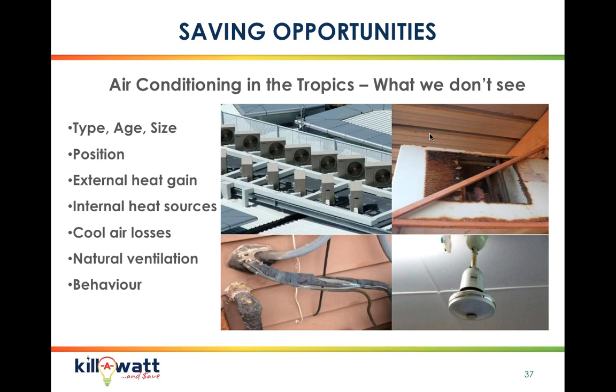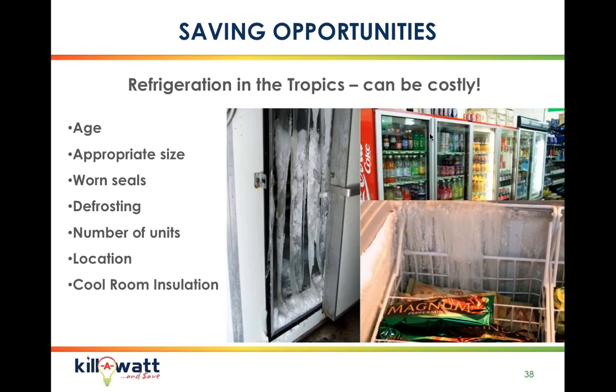In the far north, we see a lot of insulation breakdown. This is often not picked up in maintenance checks, and it's important to make sure that your air conditioning company does actually check the quality and the condition of the insulation on your refrigeration lines.